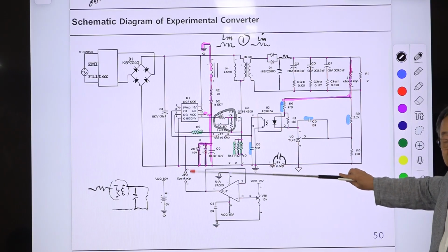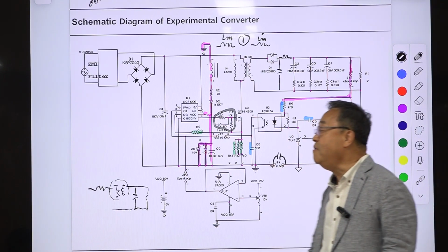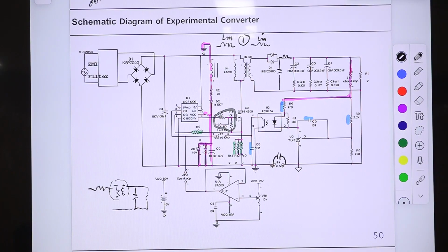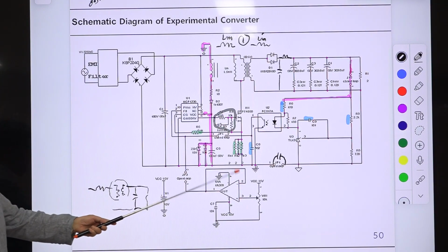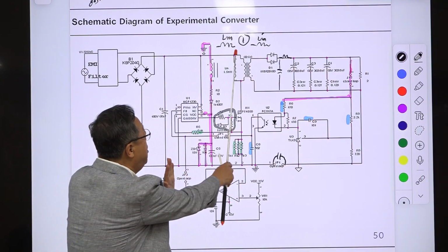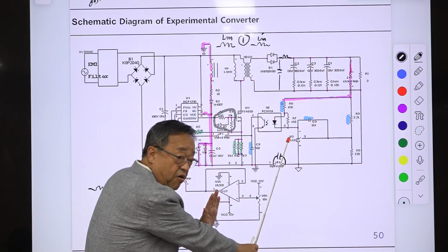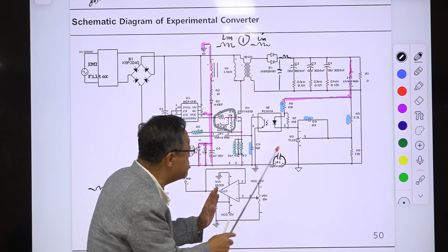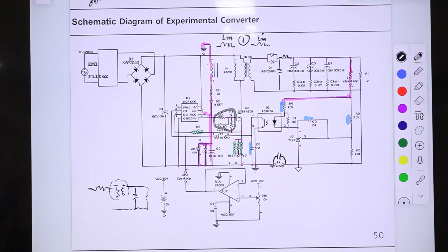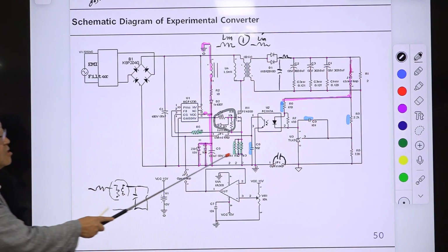But in reality, for our safety, there is a requirement by law. So we should have perfect isolation here, here, and here. This one is okay because for 60 or 100 hertz it's isolated, but to resolve the EMI noise problem, some small capacitance can be used.